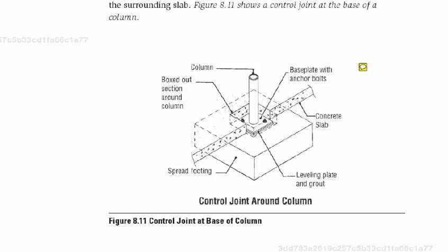project. You need to make sure that there are plenty of control joints and that they're put in. As you're building, you provide time in your schedule to do it and cost to put them in. With a tool, it takes extra time to tool them in. Or if you bring a saw in later, you have to account for the saw and the crew to bring those in. And the big diamond blades they use are expensive pieces of equipment for you to use, but you do need them. You can't build concrete without joints.